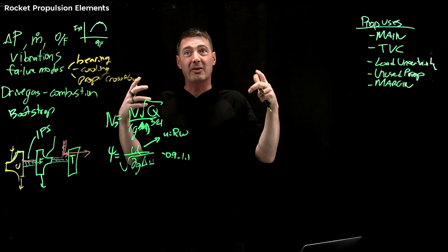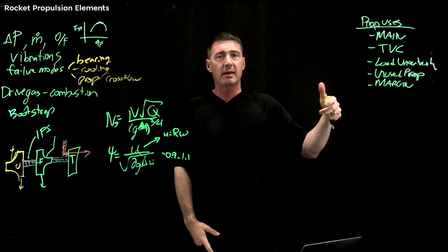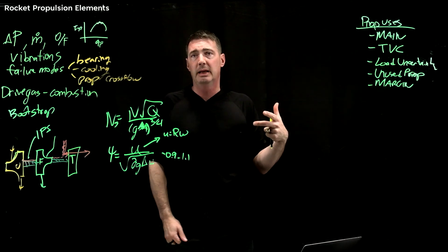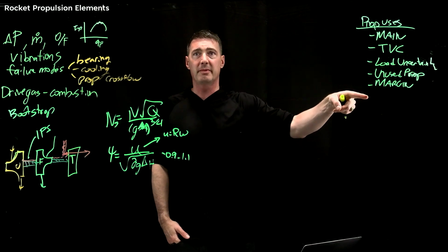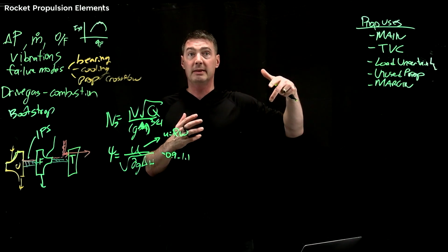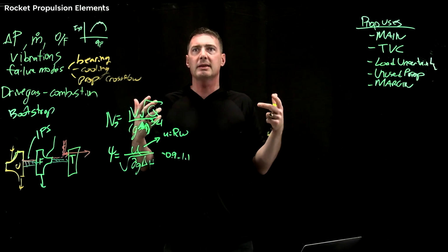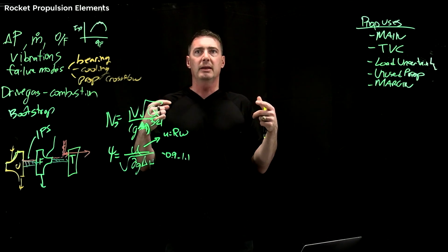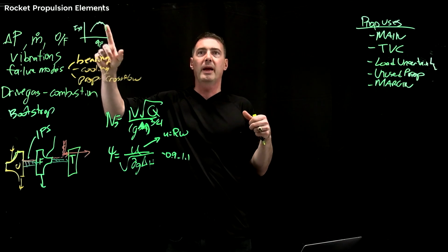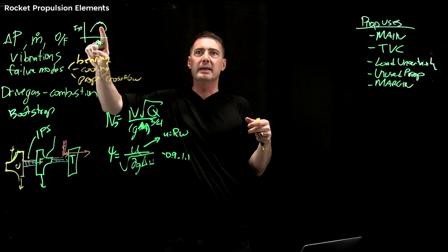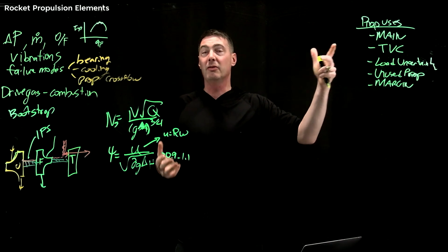Now, there are also all these other algorithms. For some reason, let's say you have some leak of ox or some leak of fuel. You need some algorithm that is observing this in flight and then saying, well, guess what? For some reason, I'm using more ox than normal, and I'm actually then going to swing over here, and I might lower my ISP a little bit more, but I will make sure I use all of the propellant.